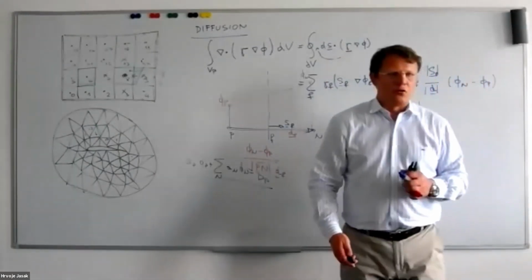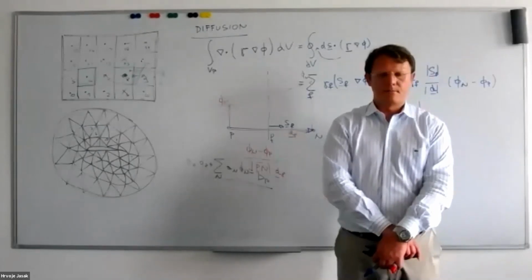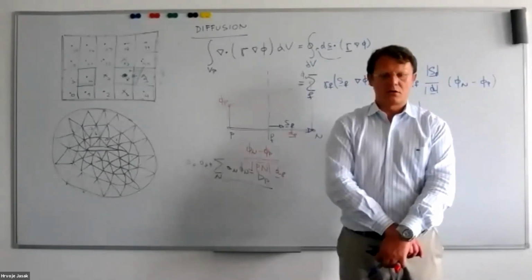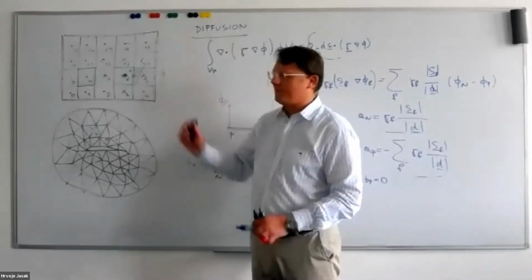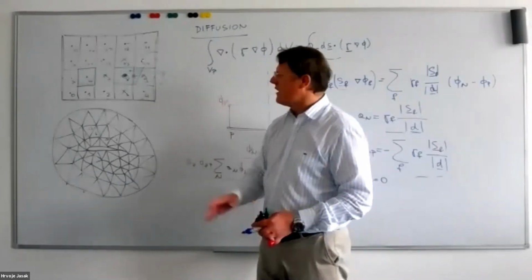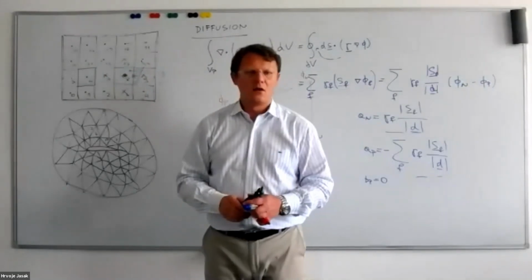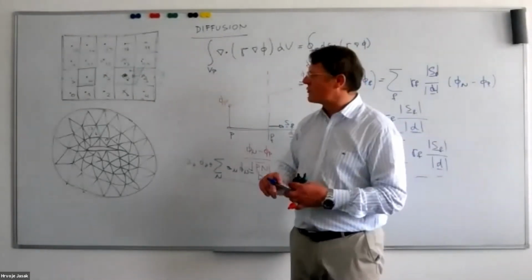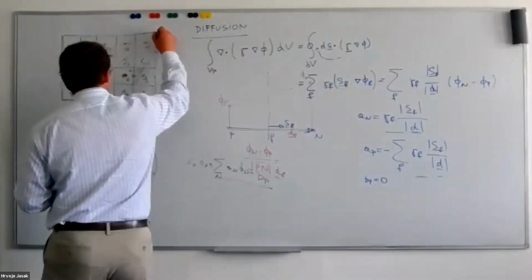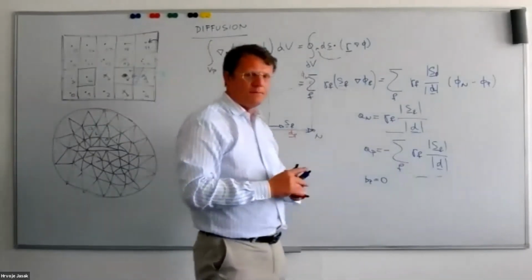To round up the story, let us talk a little bit about boundary conditions. In boundary conditions, we will specify the behavior of the variable at the outside boundary. Now, please note, internal faces have the left and the right cell, which I in the code refer to as the owner and the neighbor cell, whereas on the boundary, each boundary face is only connected to a single cell.